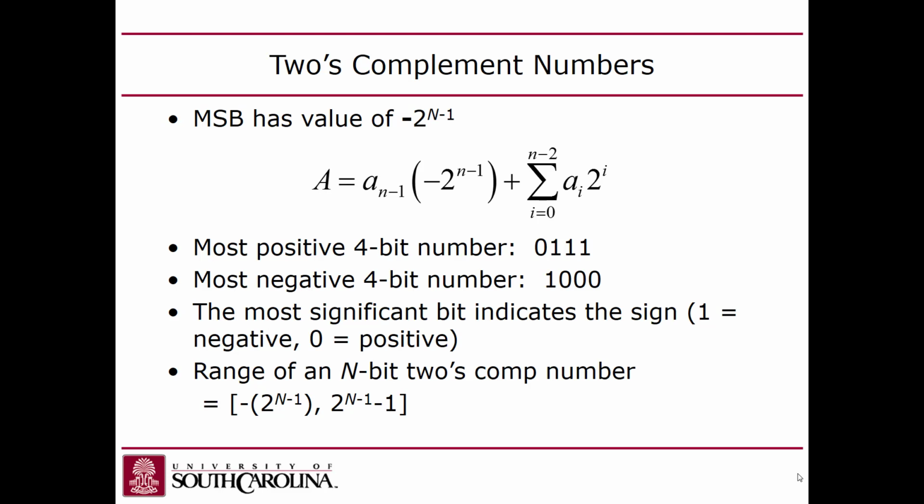So, you were saying because you added two negative numbers, then it should be another negative number, but you have 6. Yeah, it's wrong because of the overflow. So the presumption here was that the software would have to detect that and do something. The MIPS processor that you guys learned in 212 is one of the few processors that'll actually generate an exception for an overflow, if you use an add instruction.